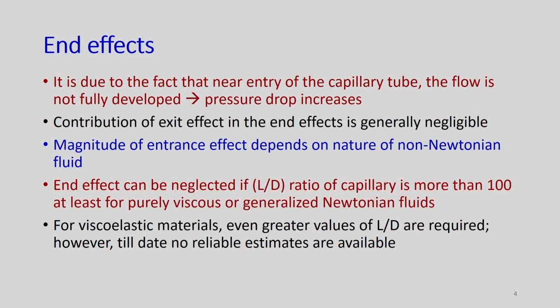So, that can be in general neglected. Okay. And then this magnitude of entrance effect also depends on the nature of non-Newtonian fluids, whether we are having generalized Newtonian fluids, time independent, time dependent, or viscoelastic type of fluid. All of them have different magnitudes of entrance effect.